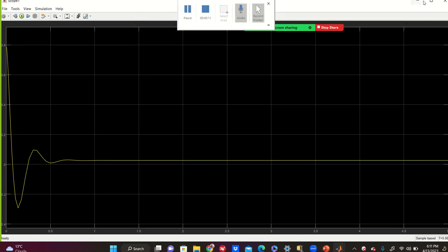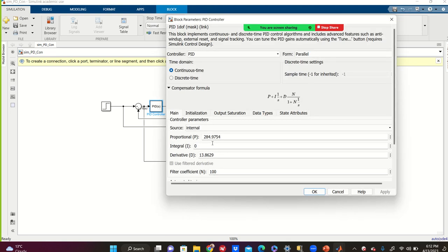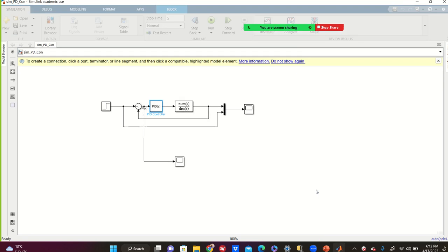Now guys, before going into detail, I need another coding style that you're gonna use when you graduate. That is the ODE style of the PID controller. But before that, let me just play with the PID controller. We did P, we did D derivative. Let me put the number of 1 or 2 for the I controller gain, KI. Here we go. Let's see what happens, guys, just for playing with that.